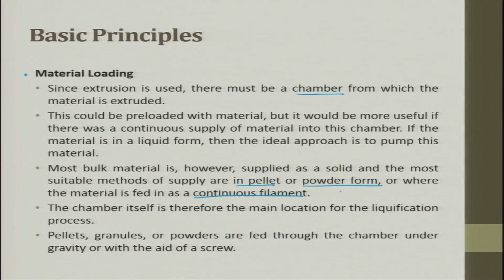If you take pellet, otherwise called powder form, it is used in injection molding where extrusion is done. The chamber itself is therefore the main location for the liquefaction process, for which, as I said, a heater is applied. Pellets, granules or powders are fed through the chamber under gravity or with the aid of a screw.